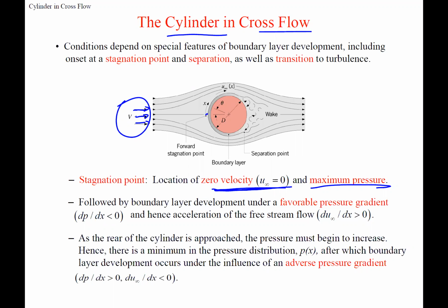Where when we were just looking at the flat plate in the section earlier, there's no pressure change here, okay? This pressure here and here and here are all the same. So we didn't have a pressure change that then changed that velocity, that U infinity. Where in this case, in the cylinder and sphere, we do, okay? So we have the zero velocity, the stagnation point, and then the velocity will increase, right, as it goes around, which comes with a pressure decrease.